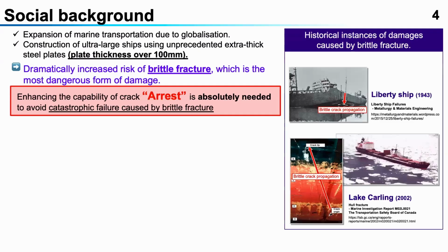So we all know that with globalization, the demand for marine transportation is increasing year by year, and engineers need to use ultra-thick steel plate to build large container ships. However, this application dramatically increased the risk of brittle fracture, which is the most dangerous form of damage. Therefore, enhancing the capability of crack arrest is absolutely needed.